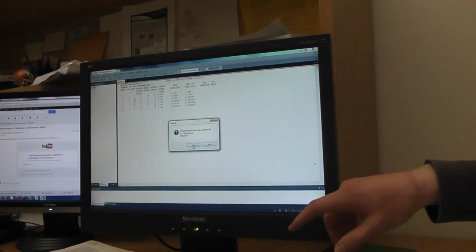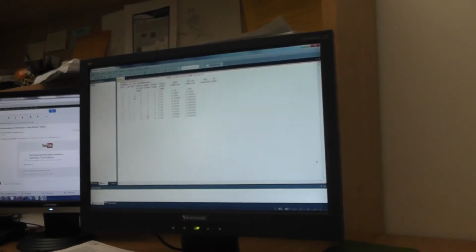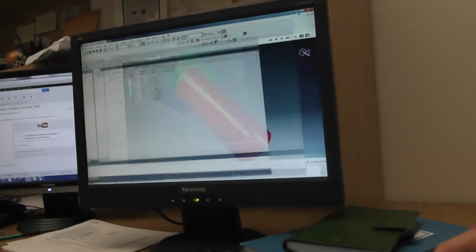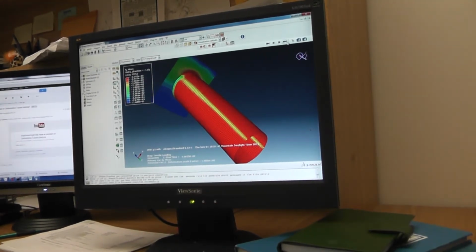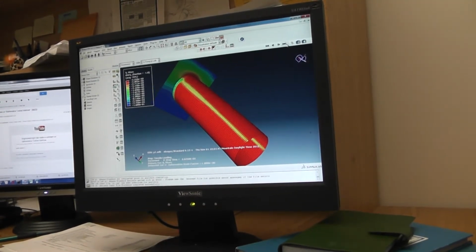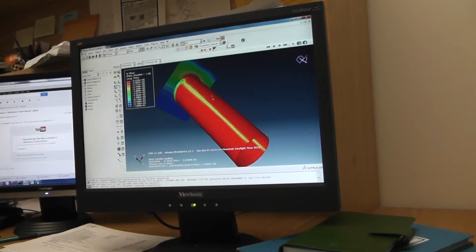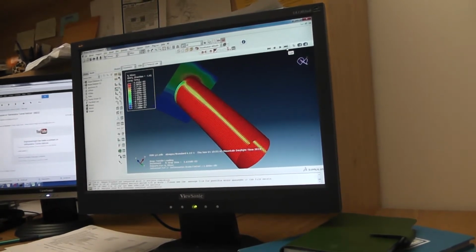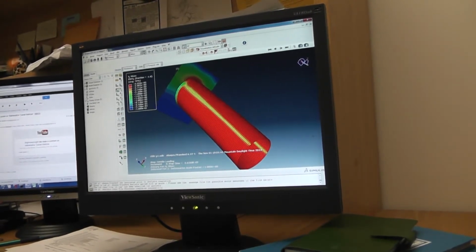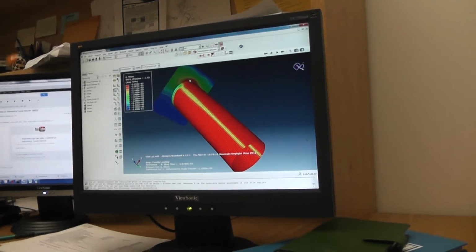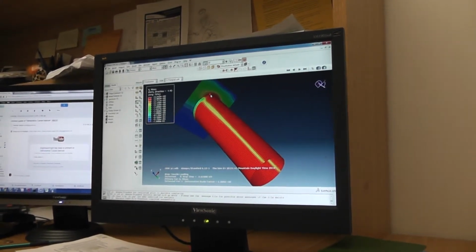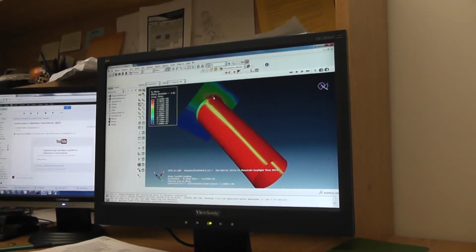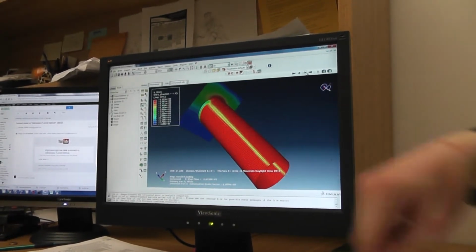We want to see the difference between pipe body and weld location, right? Yes. We don't see any. Nothing yet. This setup might not let you do that. Maybe the only way is to apply the load eccentrically, but not so much eccentrically. On one edge of the pipe, maybe?